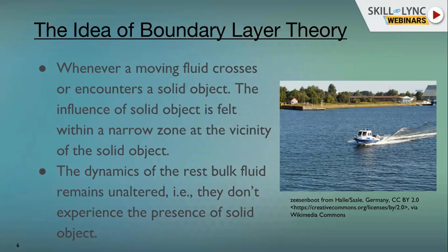Far away from the solid surface, the fluid will move with a uniform velocity, because there is no solid surface to obstruct the flow. In between, the fluid gets decelerated up to a certain fraction of area where the effect of the presence of the solid surface is felt. That region, they named as the boundary layer. We'll come to the formal definition gradually.